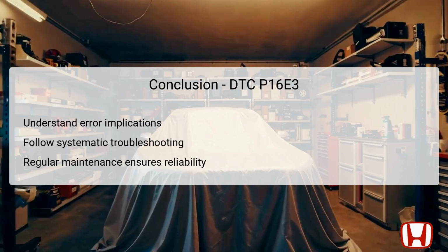Regular maintenance is equally important. Proactive checks on battery terminals and wiring can help avert issues before they arise. By keeping the vehicle in good condition and performing timely repairs, drivers can maximize performance and minimize the likelihood of experiencing DTC P16E3 again in the future.